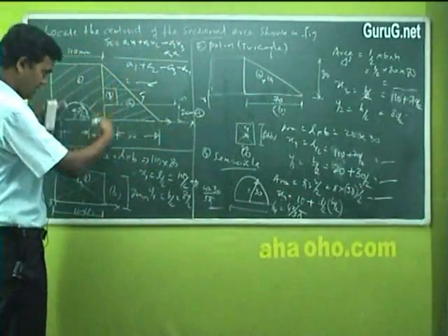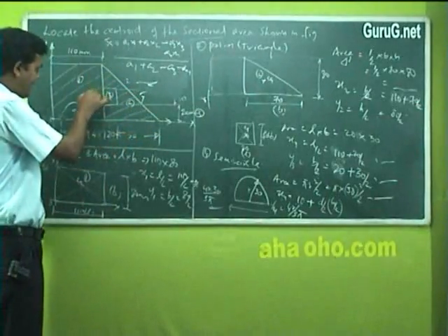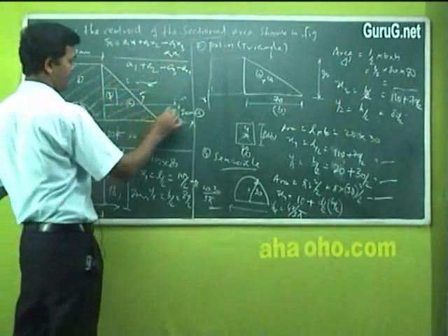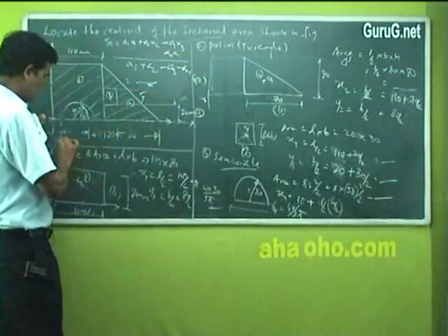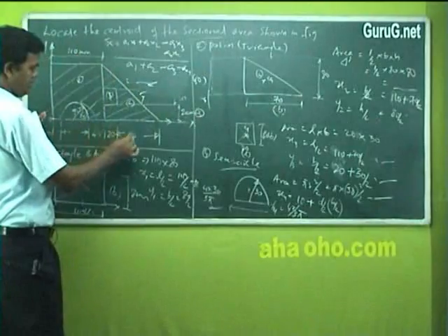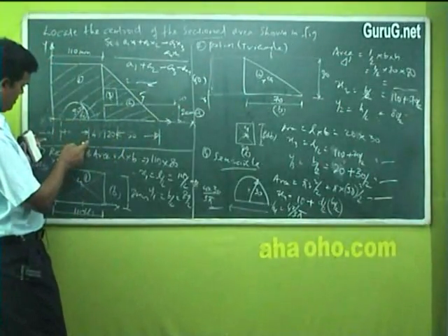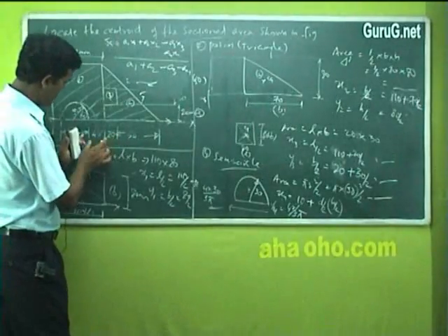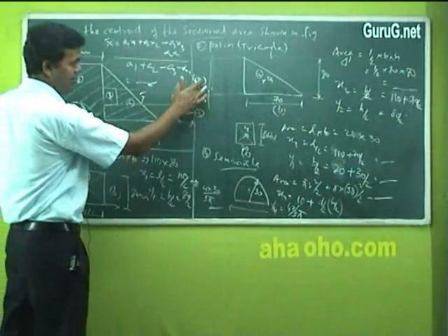Again you have to redraw the sketch. Finally this big sketch you have to draw, and indicate the value of x bar from this direction. Say suppose I get an x bar of 50 millimeter. This answer is 50 millimeter. I should indicate it in a separate sketch. Draw the sketch. This is totally how much? 10 plus 30, no, it is 60, 70, 90, 130, say 180 total. My x bar value is 50.